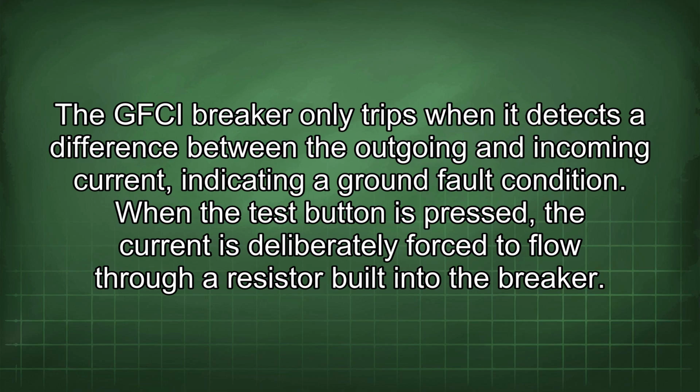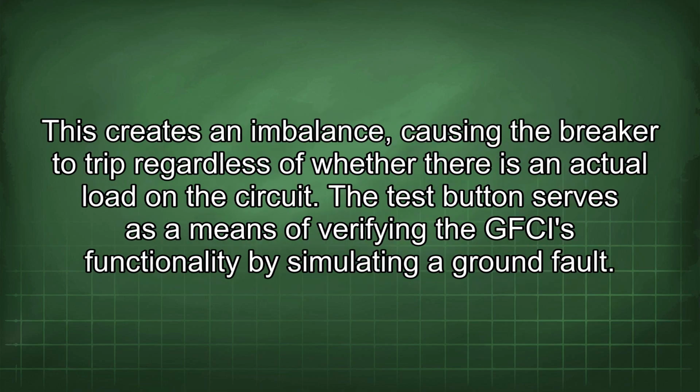When the test button is pressed, the current is deliberately forced to flow through a resistor built into the breaker. This creates an imbalance, causing the breaker to trip regardless of whether there is an actual load on the circuit. The test button serves as a means of verifying the GFCI's functionality by simulating a ground fault.